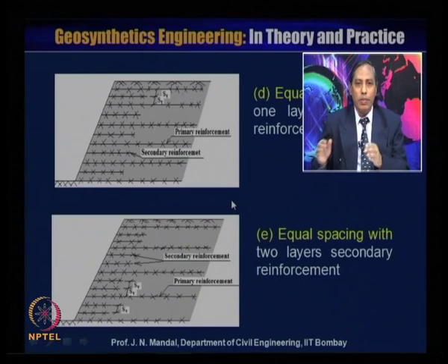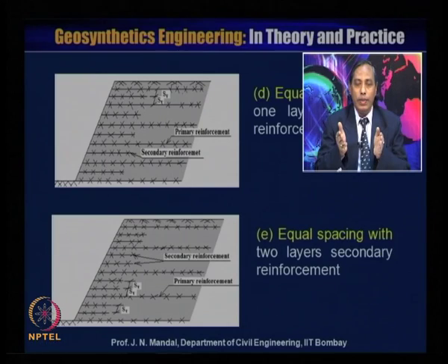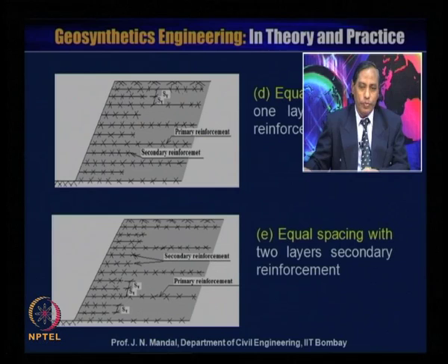Sometimes, if the spacing between the two primary reinforcements is 1 meter or more than 1 meter, then it is necessary to provide secondary reinforcement. So sometimes one layer of reinforcement is used as secondary reinforcement, and sometimes two layers of secondary reinforcement are required.